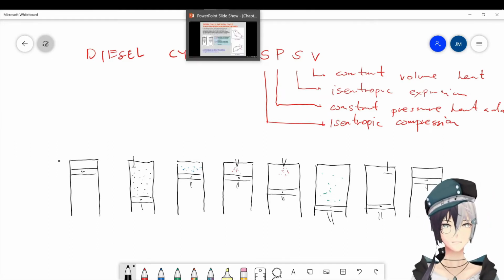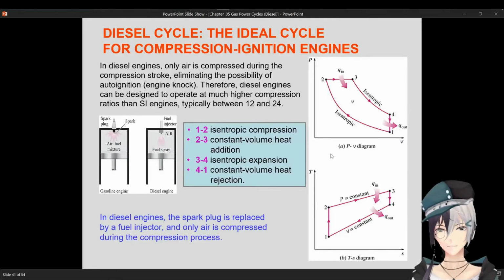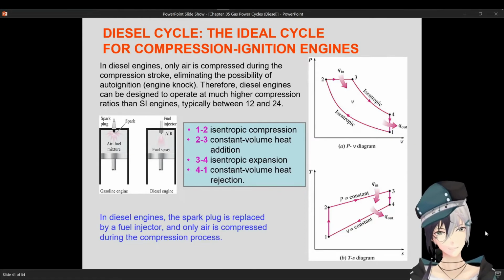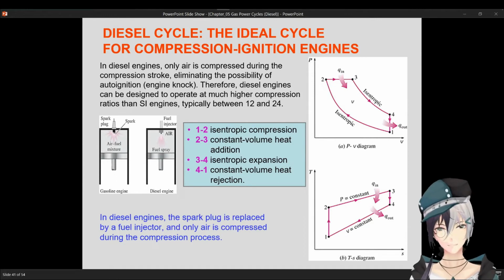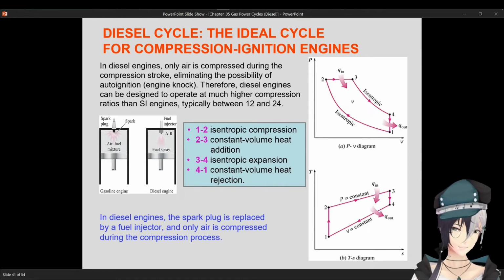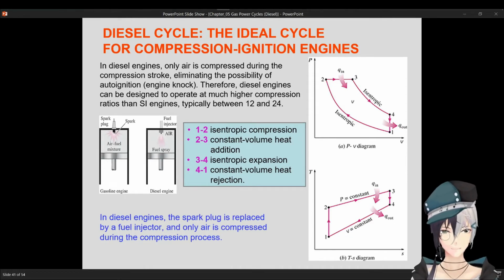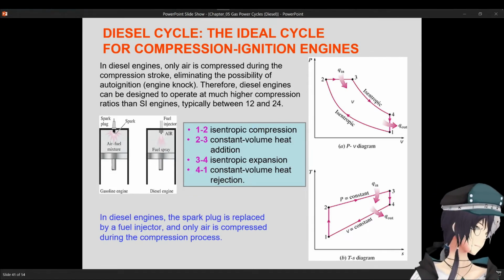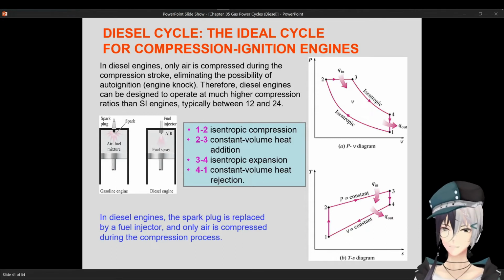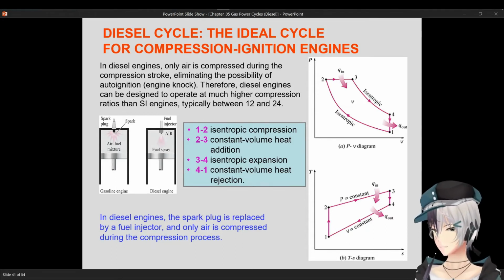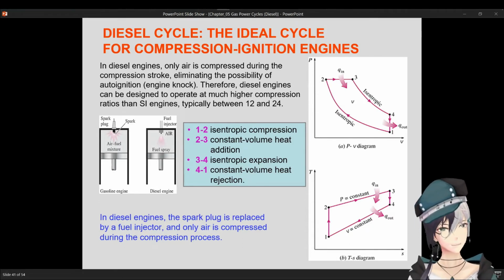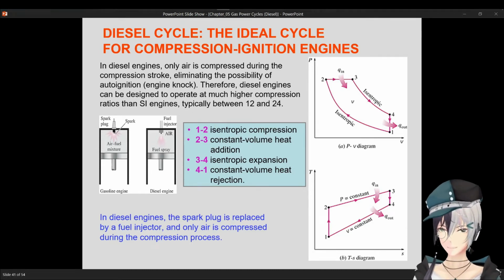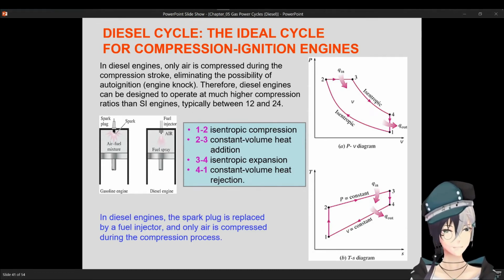Okay, so illustration of the diesel engine. So another difference between the diesel engine and the gasoline engine is that instead of using a spark plug to ignite the air and fuel mixture, you have your fuel injector, wherein air is only compressed during the compression stroke.